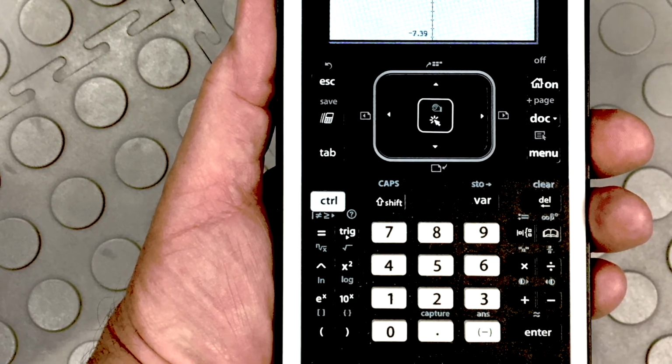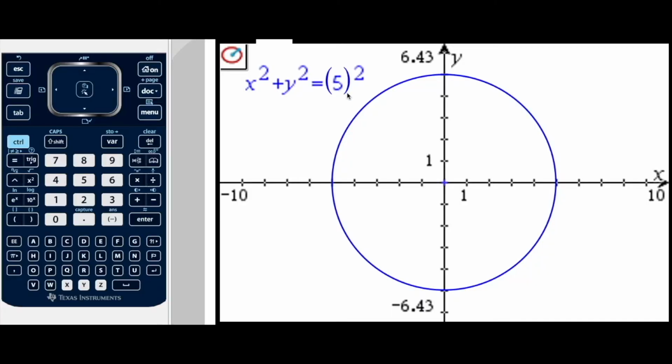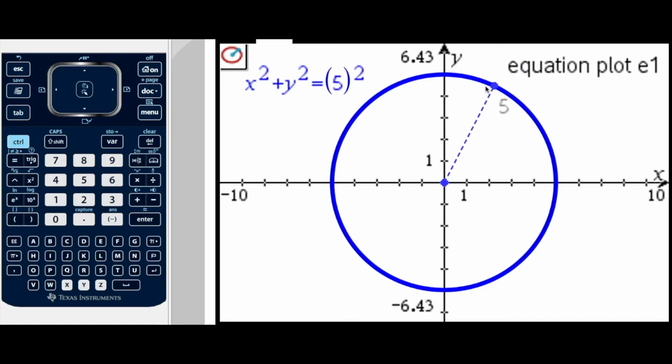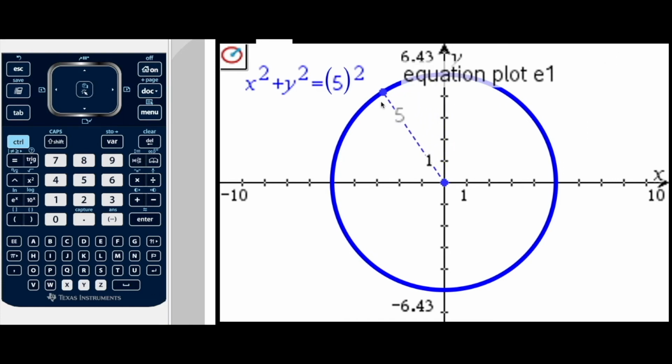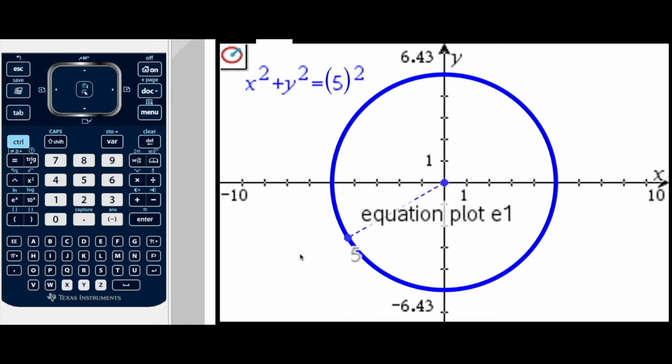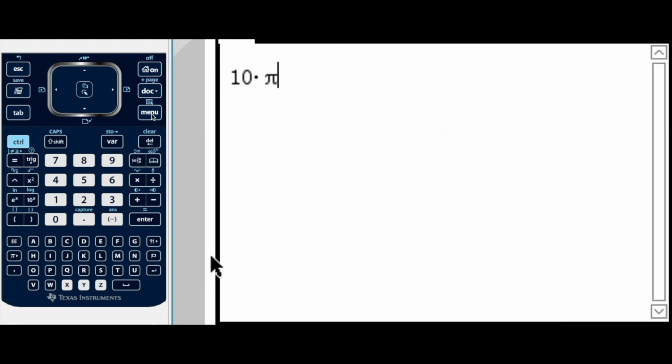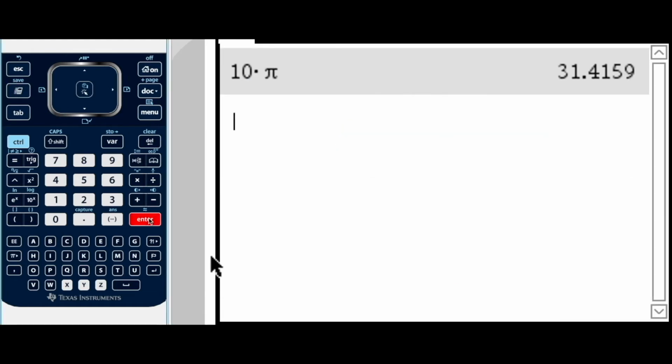So let's say you were standing in front of a steel pipe that was miles long and you wanted to find the diameter of that pipe. If the pipe was 10 inches in diameter, but you didn't know that, and you put a regular tape measure around the pipe, it would read 31.416. If you took that number and divided it by the number pi, you would get the diameter of the pipe. But there's an easier way to do this.